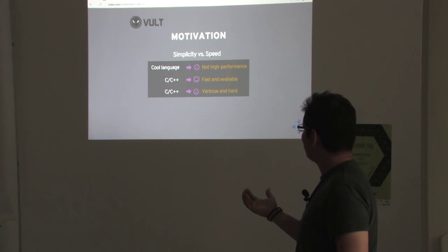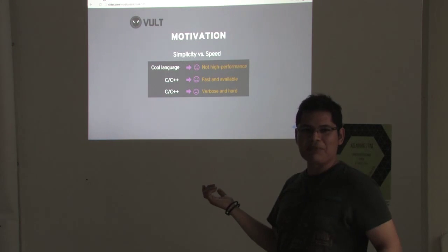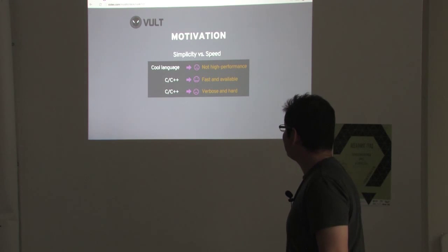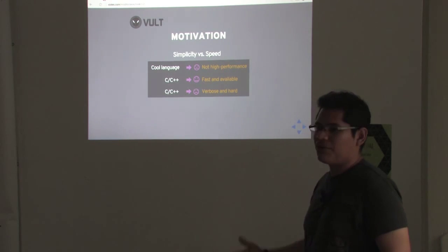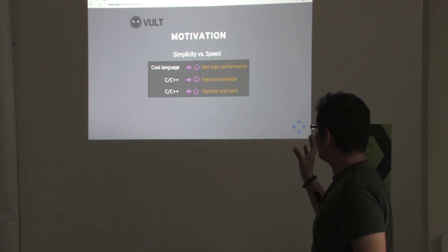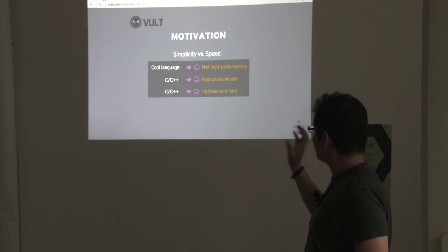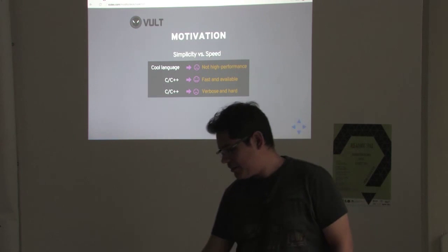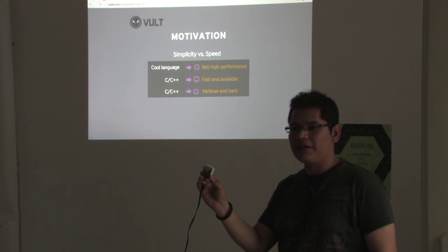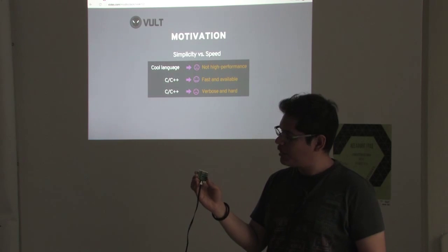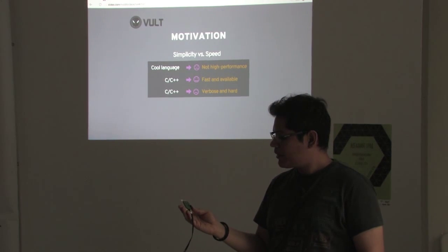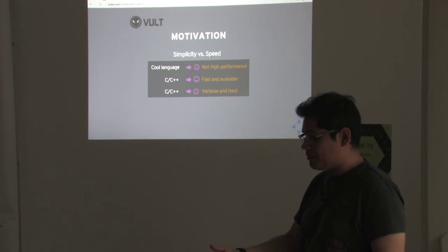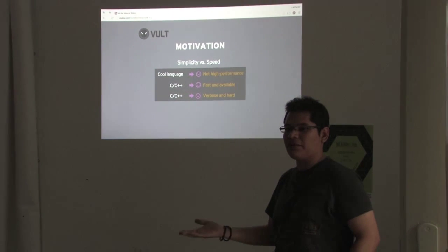programming this kind of system is that if you want to use a nice language, something more modern, like JavaScript, Python, or something like Rust or Go, you just cannot achieve the high performance that is required for these applications. And even if you run it on a board like this that has a small ARM processor, the problem is the real-time constraint that I was mentioning before. It may be able to complete the computation, but it takes too long.